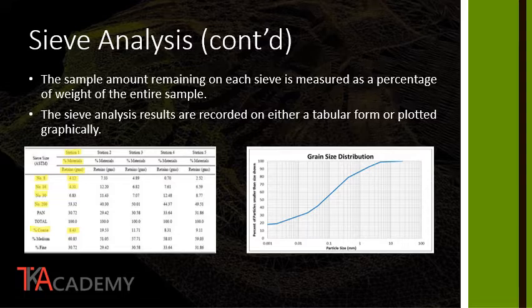On the number 30 sieve, we had 6.83 and 53.32% retained, and that equals the medium coarse materials equaling 60.85%. Pan is the amount of everything that went through the smallest sieve, which was 200, and that percentage was 30.72. That results in the amount of fine grade material at 30.72% of the total sample.